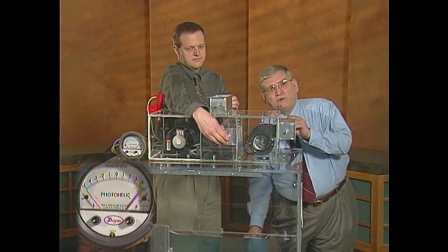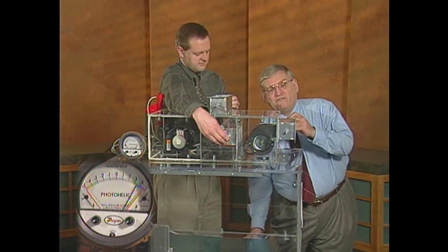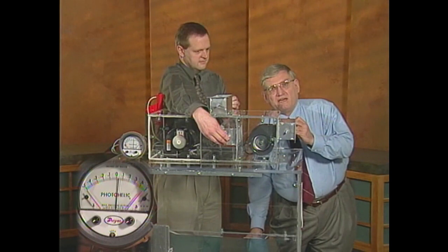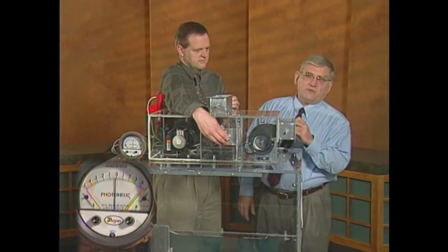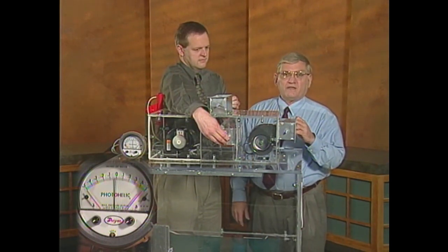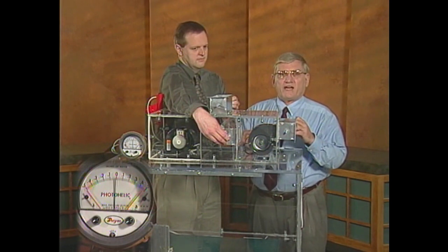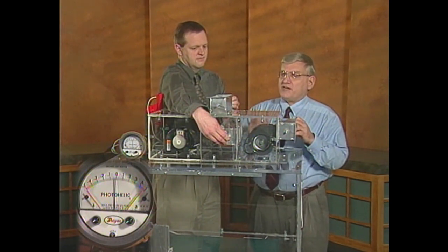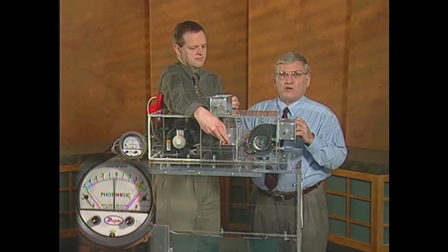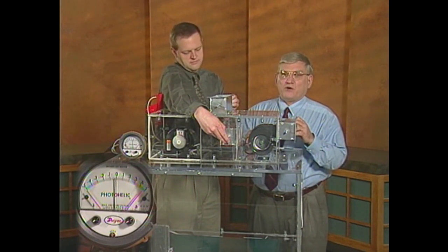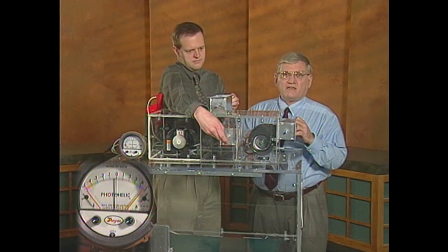To control that, we would then turn on the central relief fan and at the same time open the relief damper to its full position, thus bringing the space back close to neutral static pressure. As the outside air damper modulates closed in the modulating economizer mode, you'll see a slight decrease in space pressure.